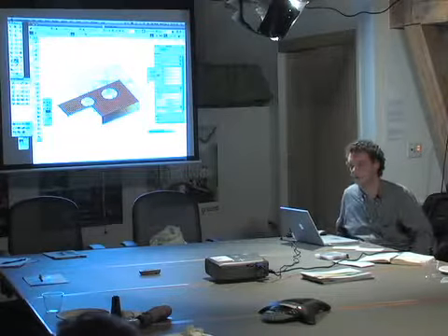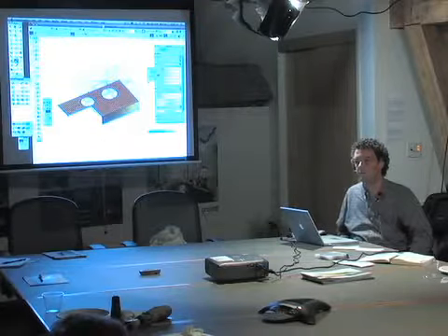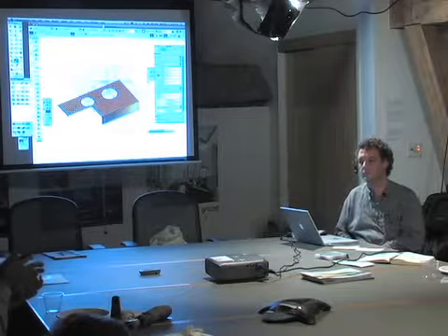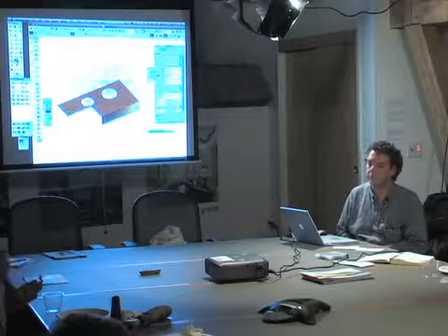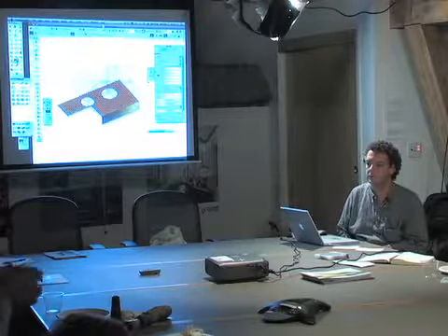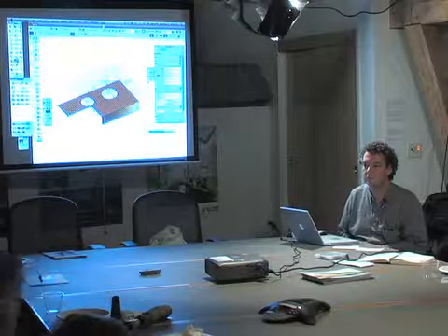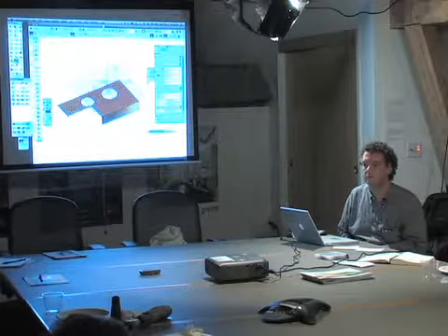Another thing I noticed, if you have multiple layers, let's say 2 walls on top of each other, a second floor wall and a first floor wall, you can view both of those layers at the same time, but you actually have to extract both of those surfaces, which you can do, and then you have to combine surfaces so that it's all one continuous polygon that you can then add a texture to. I noticed that too.